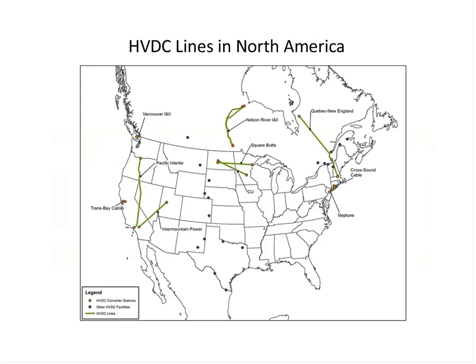Yeah. Here. The first major DC line was Cahora Bassa in Mozambique, on the Zambezi River, to South Africa, which is about 1,000 kilometers. And one of the reasons they put it there is those long distances, the inductive losses become overwhelming, whereas the ohmic losses, obviously, are just a question of voltage, right? But I think the key thing to think about, Mike, regarding the question, is that there were some DC lines that were removed. It's not DC in itself. You have to look at the entire system and think of the conversion process and the quality of the conductor. All of those things are important when you evaluate whether you want to keep a system or not.